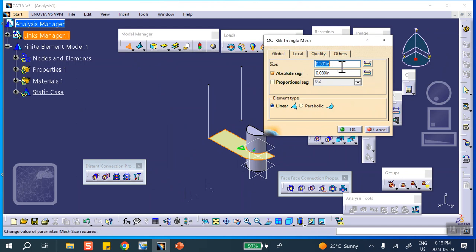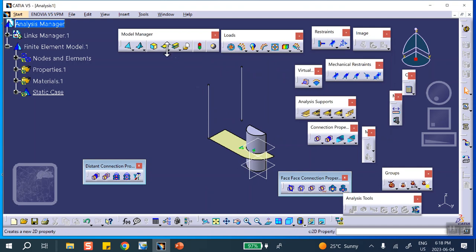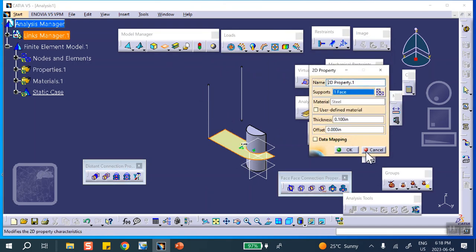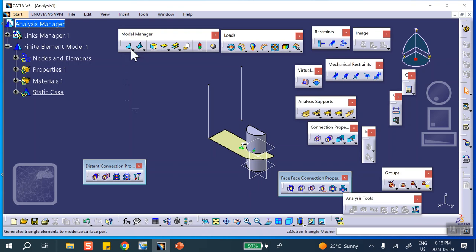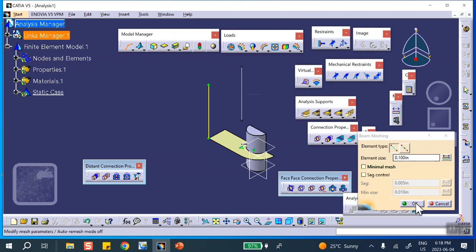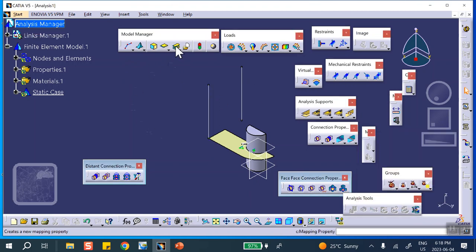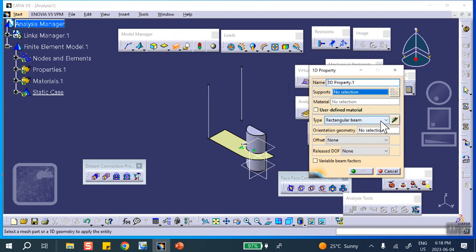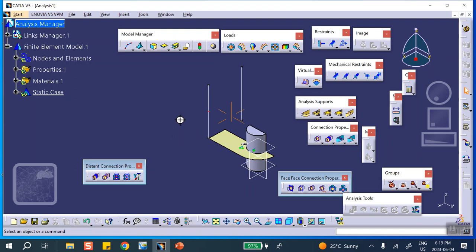This, yeah, okay, 0.1, 0.2, and give it a thickness. And we're going to mesh it with beam element. Sorry, mesh this line with beam element. Don't mesh the other one because we don't want it to participate, and give it a cross-sectional property. So these are correct because we just used it a minute ago. Actually, what is it that you want to give it properties? This. And what is the orientation point? For example, that corner point will do the job, or that corner point for that matter. Doesn't matter. Everything is the same.